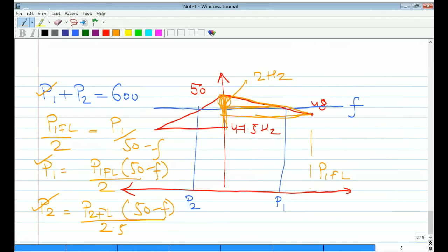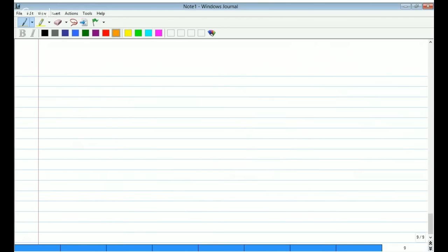A 200 volt DC shunt motor, 17 kilowatt output with an input of 20 kilowatt. Field winding resistance 50 ohm, armature resistance 0.04 ohm. Maximum efficiency is obtained when copper loss, or variable loss, is equal to constant loss.